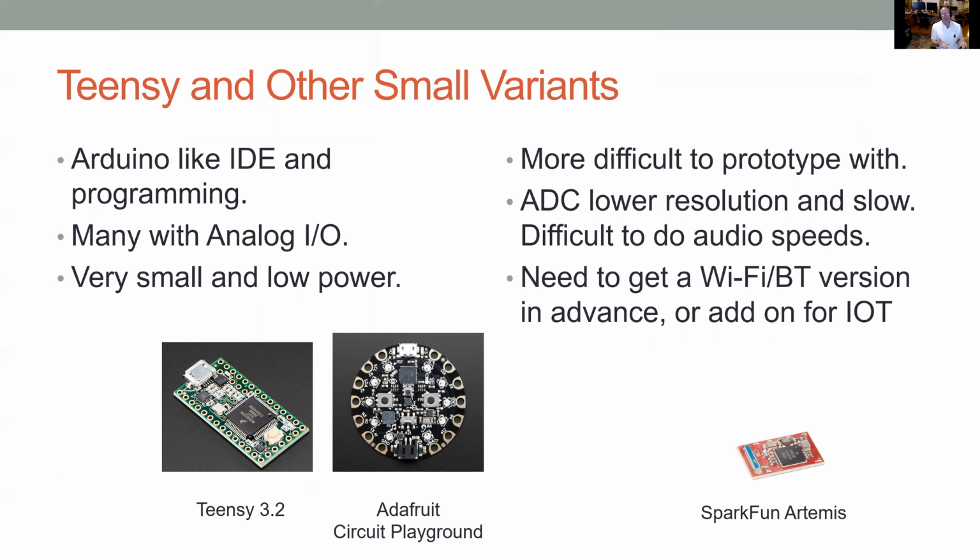There's some variants of Arduino, like Teensy, SparkFun Artemis, and the Adafruit Playground. They have IDEs very much like Arduino. The Adafruit Playground also has a version that uses MicroPython if you're a Python fan. They're very small, low power, but you know they're a little more difficult to prototype with, and you still have the problems like the Arduino with the slower ADCs, and you need to think of in advance if you want Wi-Fi, Bluetooth.